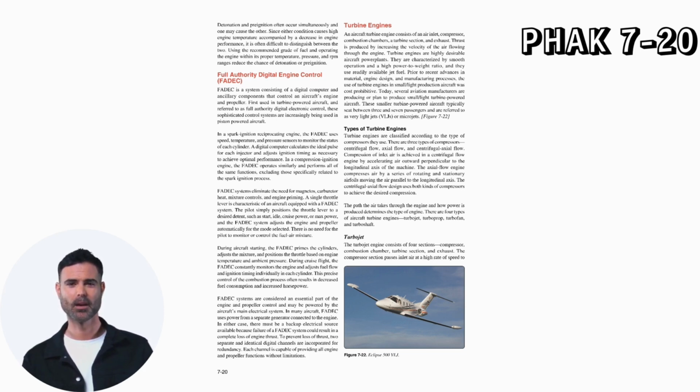FADEC systems are considered an essential part of the engine and propeller control and may be powered by the aircraft's main electrical system. In many aircraft, FADEC uses power from a separate generator connected to the engine. In either case, there must be a backup electrical source available because failure of a FADEC system could result in a complete loss of engine thrust. To prevent loss of thrust, two separate and identical digital channels are incorporated for redundancy. Each channel is capable of providing all engine and propeller functions without limitations.